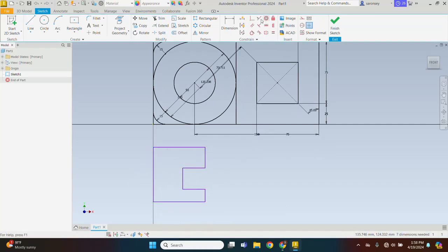Now choose the collinear constraint command. So we click on it, and this is what it does. So find any two lines. Let's apply the constraint between this line and that line. So what happens is it puts them on the same line. If we want to make this also fall on the same line with this, then we can select the two, and that is it. You can right click, okay.